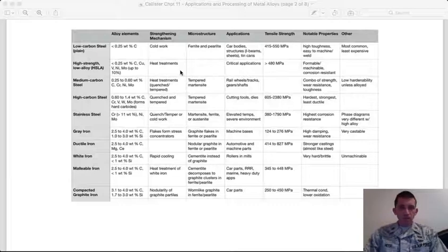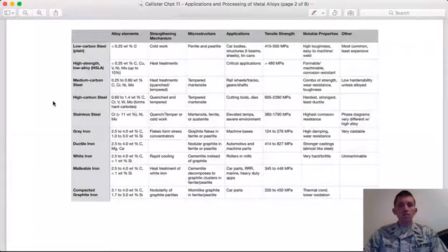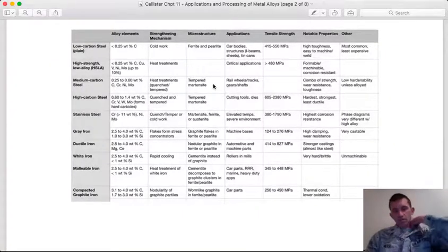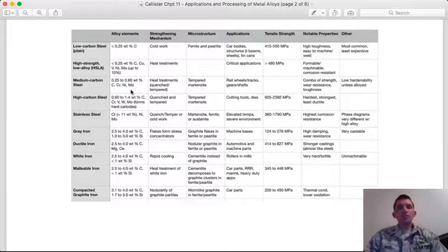And we'll see again with the Jominy end quench test that these higher grades of steel with alloying elements are much more hardenable, meaning you can quench them and actually get the heat out of the center of a part before, let's say, ferrite or pearlite is formed. So they are more hardenable.